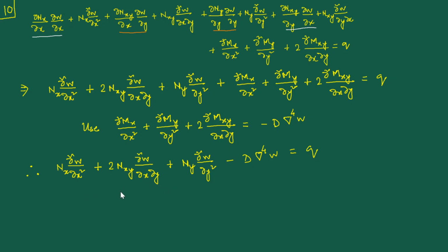Now, the next step that we're going to follow has its motivation in that effective two-dimensional reduction, which is to say that back in applied elasticity, when we were dealing with the 2D elasticity chapter, we had expressed the stresses in terms of a single scalar function, in terms of its derivatives, using the Airy stress function, and we are going to do a thing which is exactly the same. So we write this nx, nxy, and ny in terms of this scalar function.